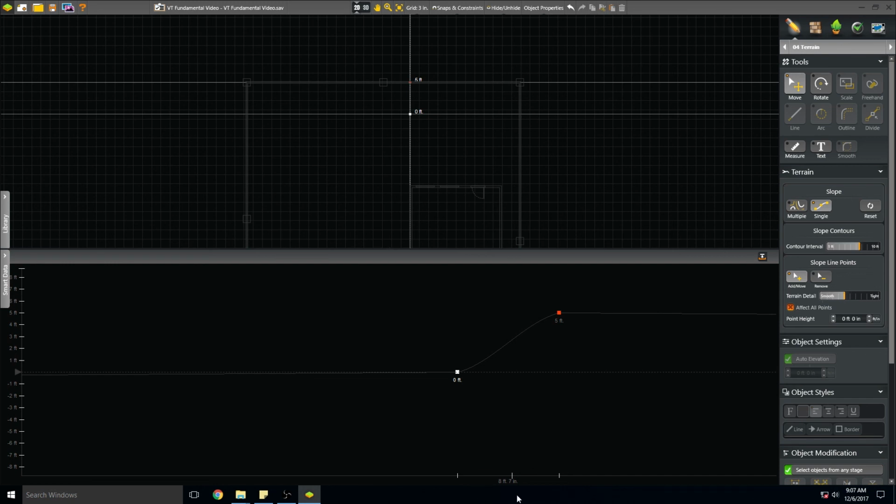You can set that distance by left-clicking and dragging the 0 in the top half of the screen. So let's say that we've gone out and we've measured, and we know that that distance should be exactly 10 feet from 0 to 5. So just take your cursor up to the top half of the screen, left click on the 0, and either take it further away from or closer to the 5. Watching down at the bottom, when you get to 10 feet, that's the distance that you want.